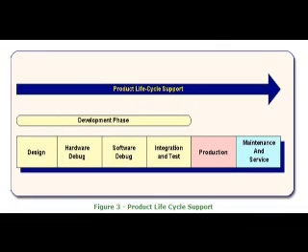Boundary scan technology is the only cost-effective solution that can deal with the above problems. In recent years, the number of devices that include boundary scan has grown dramatically. Almost every new microprocessor that is being introduced includes boundary scan circuitry for testing and in-circuit emulation. Most of the CPLD and field programmable gate array, FPGA, manufacturers, such as Altera, Lattice and Xilinx, to mention a few, have incorporated boundary scan logic into their components, including additional circuitry that uses the boundary scan four-wire interface to program their devices in system.